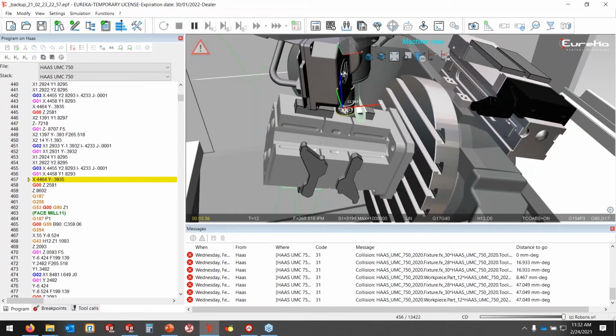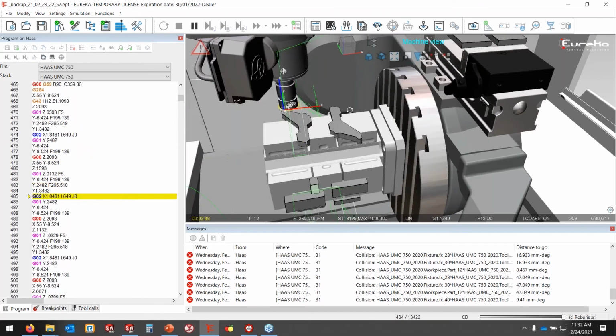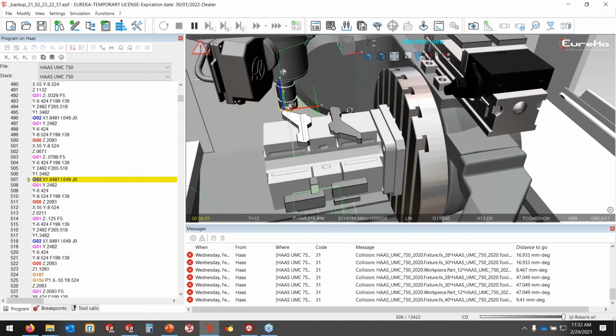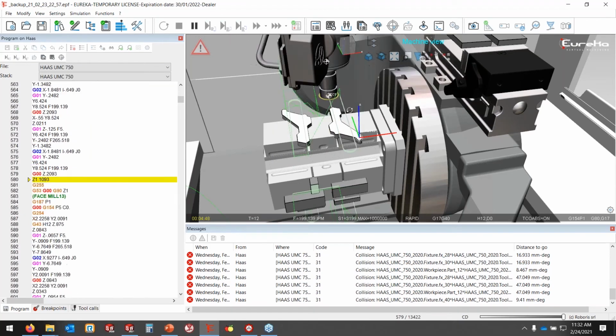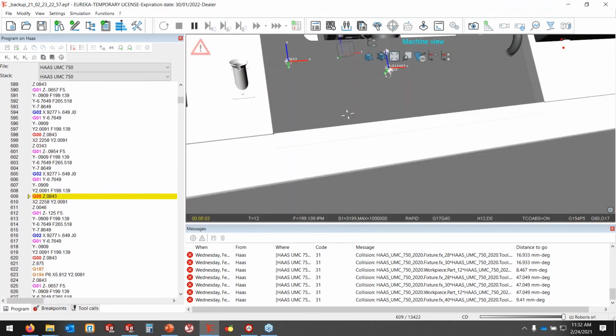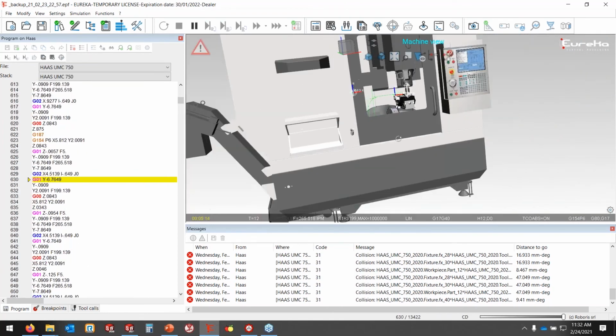Daniel, it's an aluminum jaw, right? So yeah, I'll just slow it down on the first pass through. I can either cut a notch in there and get that out of there, or I can just slow it down, let the face tool take the first pass off, and then from there I can speed the program back up. I just have to pay attention to that now you pointed it out.